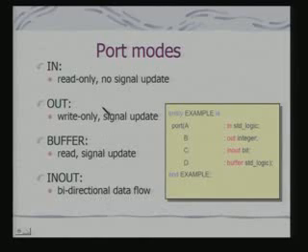Then, in the black box, what we have used is port. Okay. So, ports can be in, out, buffer, inout. So, if it is an in port, there is no signal update, out is write only, so there has to be a signal update.